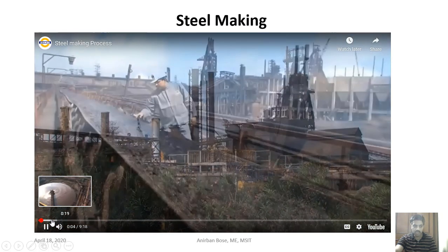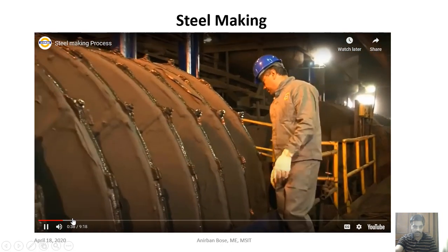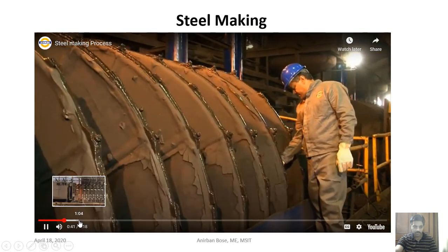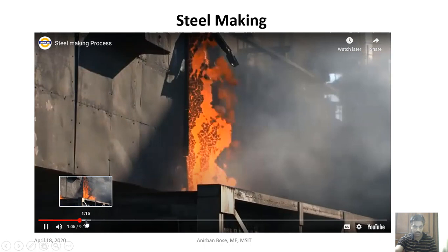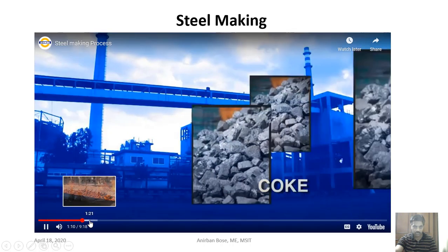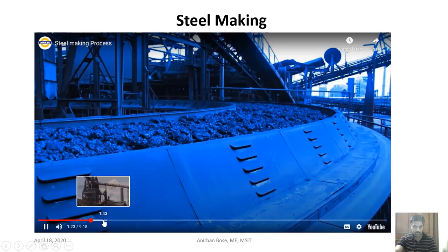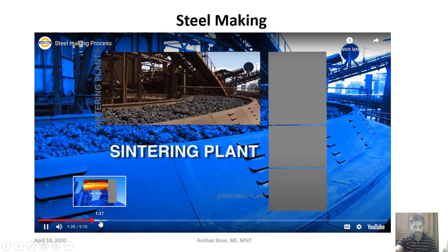The initial part you have already seen. In the process, the sludge is subjected to filtration. The water is recovered and the dry ore is sent to pelletizing. In hours of baking, the coal is transformed to coke, the basic fuel for the blast furnaces that produce pig iron, or first fusion iron. Another raw material for the blast furnaces is sinter, a porous mass.